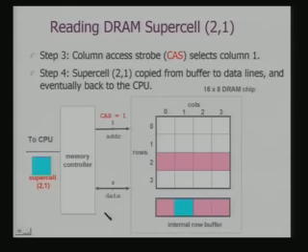This is a typical read operation for DRAM. Similar is the write operation. Another interesting feature to note is that the refresh operation is nothing but a dummy read. If I do a dummy read, I can actually refresh the cells.